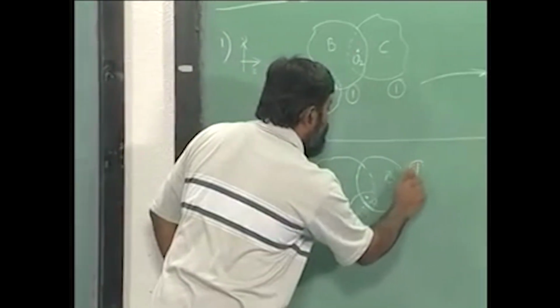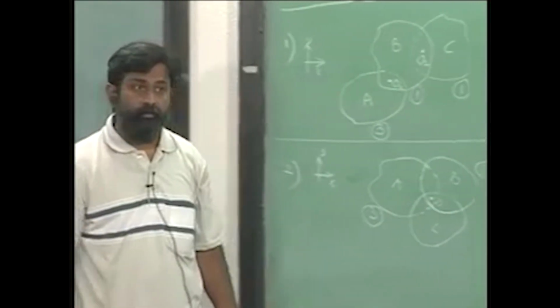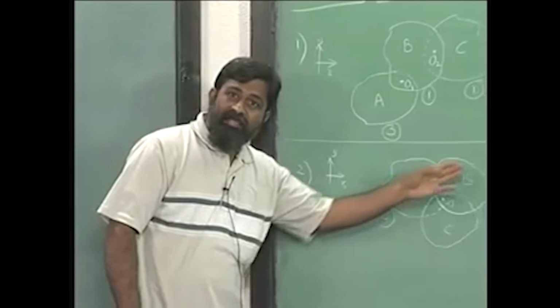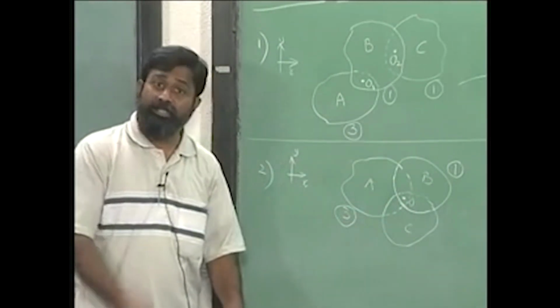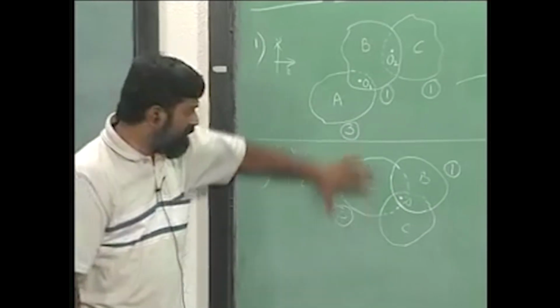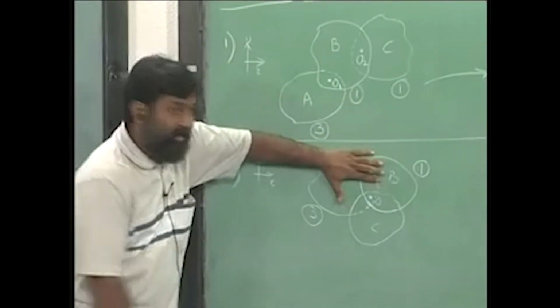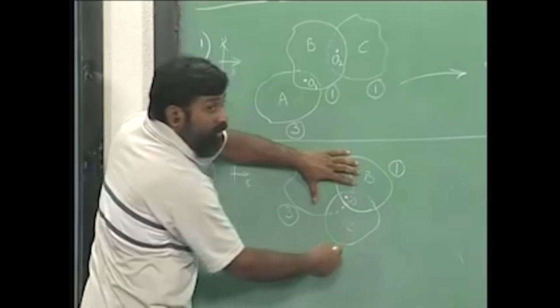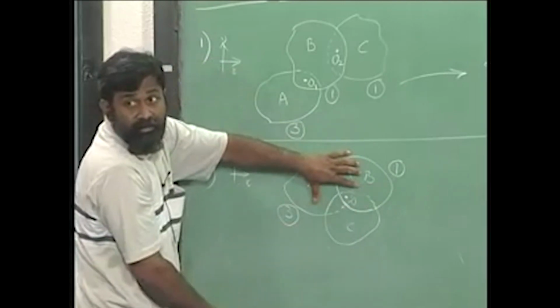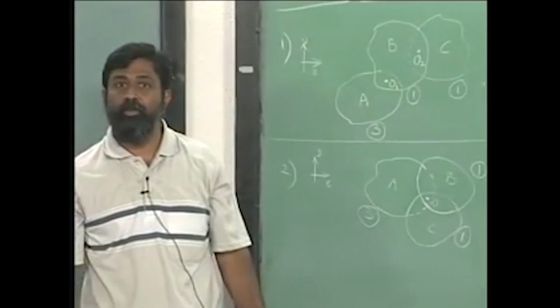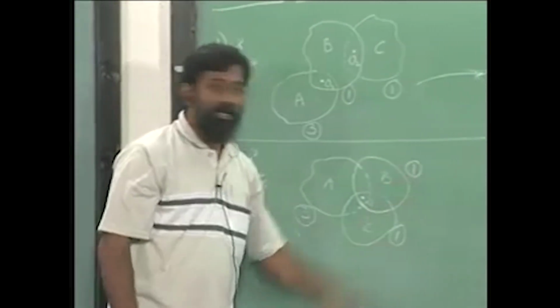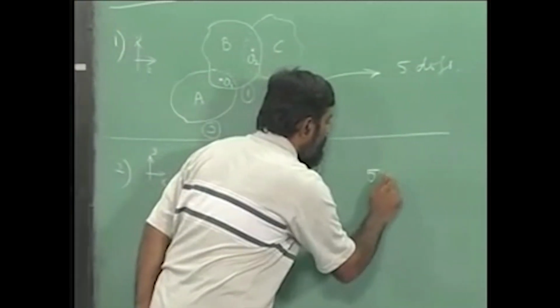So B can have 1 degree of freedom. Now I will fix A as well as B and look at C and ask the question whether there will be movement at all. The answer is yes, because this is a pin and the body C can move independent of A and B, or in other words this will have an additional degree of freedom to move. If I add the total, I will have 5 degrees of freedom possible.